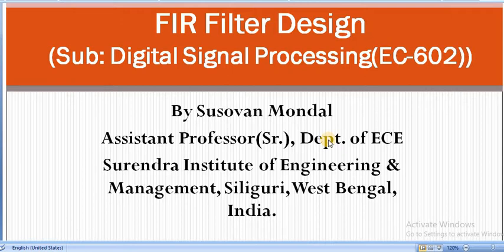One main advantage, or difference, is that with an FIR system we can design an exact linear phase system. In communication, this linear phase system is very important. If we design an exact linear phase system, then the reception of the signal at the receiver will be very faithful. So the linear phase response is very important, and this linear phase system can be implemented by an FIR filter.